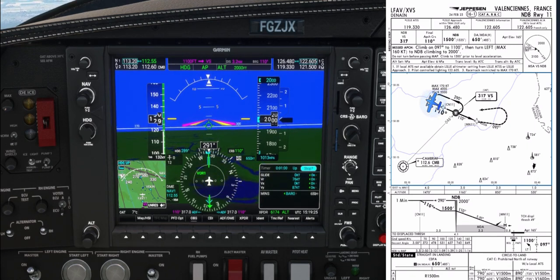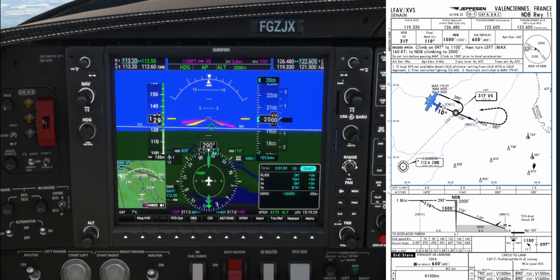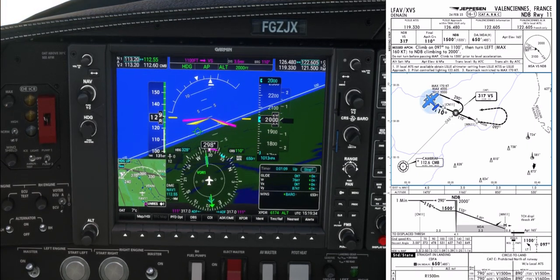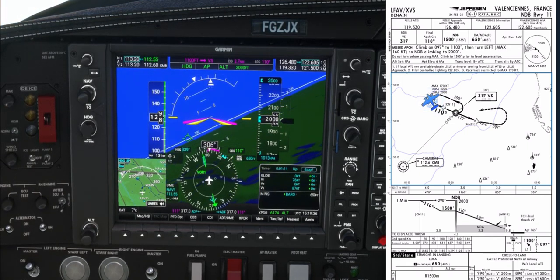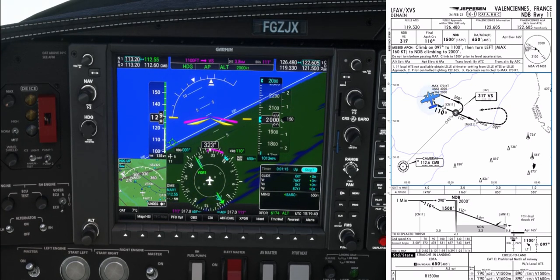As for each turn, we proceed with the next step concept. Turn towards the beacon, time, off, reset, twist, heading bug, talk, nothing, throttle, check power versus speed and icing clues. Next step will be, overhead the station, turn left on the outbound track.